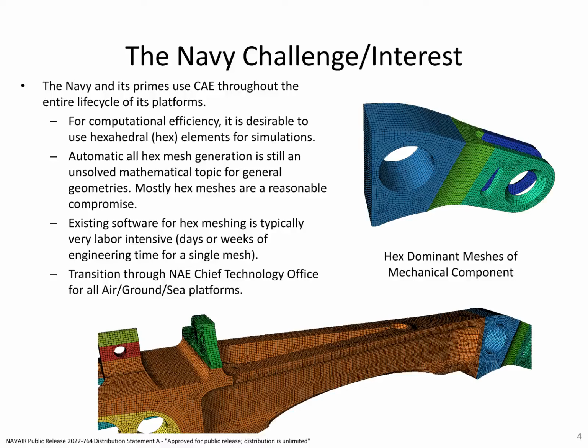A hexahedral element is basically a brick, and unfortunately, the generation of these types of meshes tends to be very manual and time-consuming, because fully automatic hex meshing is still an unsolved mathematical problem.